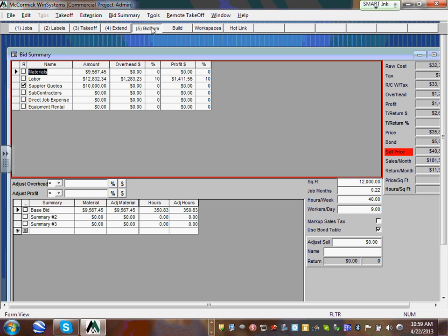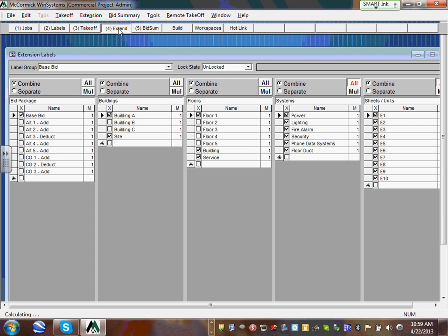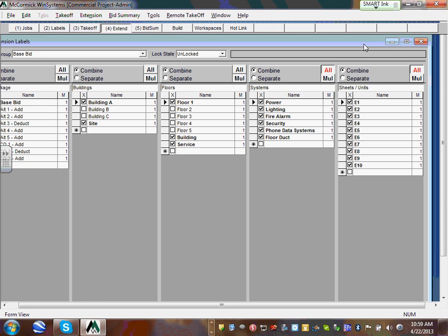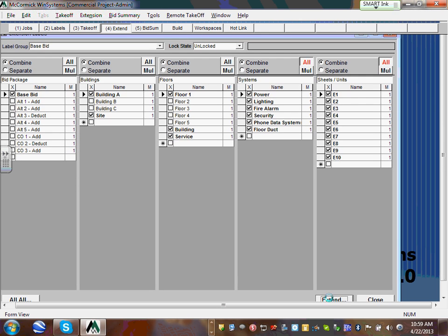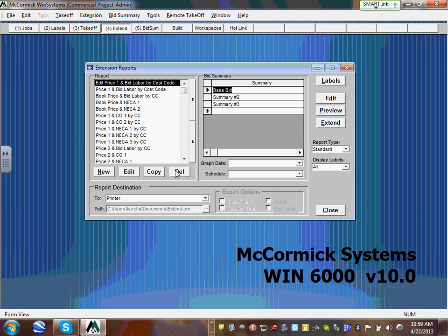When it comes to lighting circuits and receptacle circuits, always group them in conduits. You'd be a fool to take 1/2 inch for every branch circuit all the way to the panel. Any comments, guys? Any questions about that? So that's really what the whole software is. When we do the extension, there's not a whole lot to it. Like I said, in 2-3 hours, there's a lot of stuff you can play with.